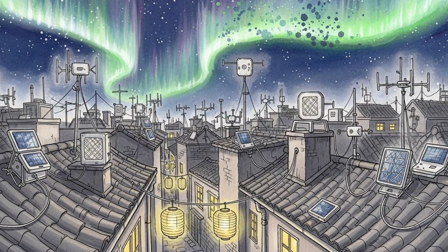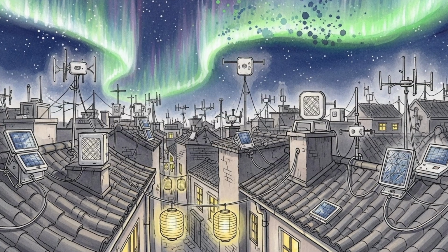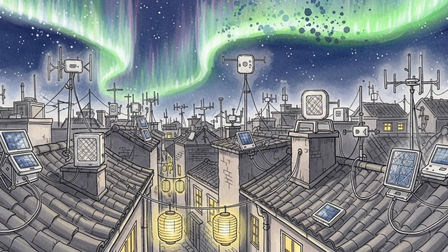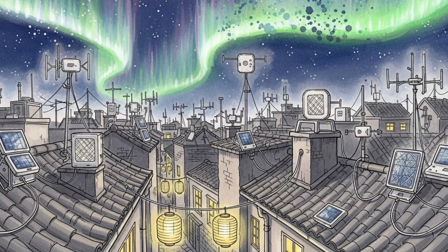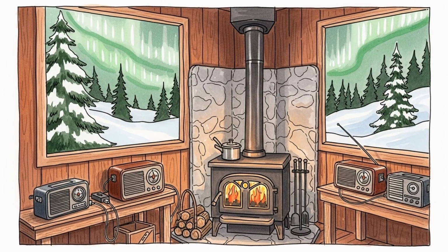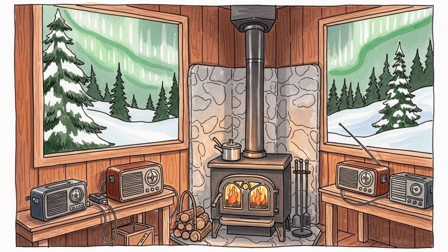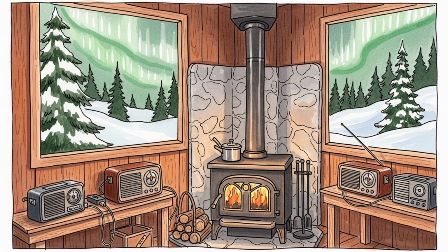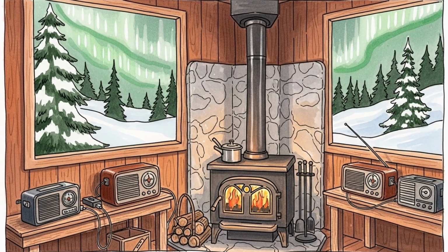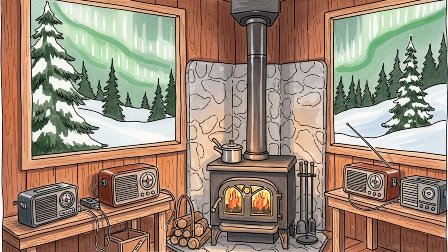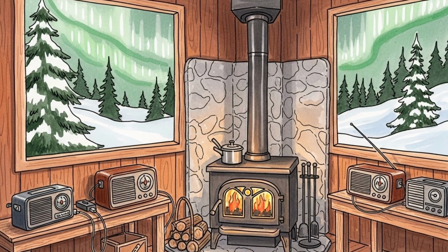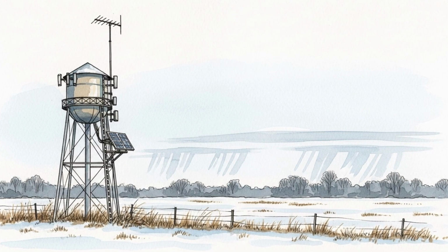Part 10. Impact Scenarios and Recovery. This part assembles realistic impact scenarios, the order of failures, and the steps for stabilization and restoration. It uses the same chain of cause and effect described earlier. Triggers are a fast coronal mass ejection, high solar wind pressure, and sustained southward BZ. Ground stress is set by the rate of change of the magnetic field, called dB/dt, regional conductivity, and conductor geometry.